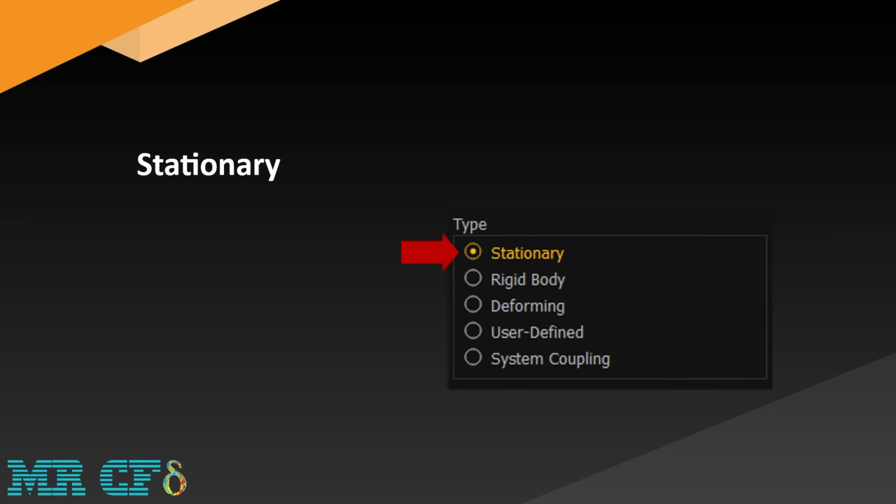For example, if a cell region is assigned some solid body motion, the location of all nodes belonging to the cell region will be updated, even if some nodes are also part of a non-moving boundary region. The explicit declaration of a static region excludes the nodes in these areas when updating the location of the nodes. That is, it makes that area not affected by mesh changes caused by moving or deforming areas.